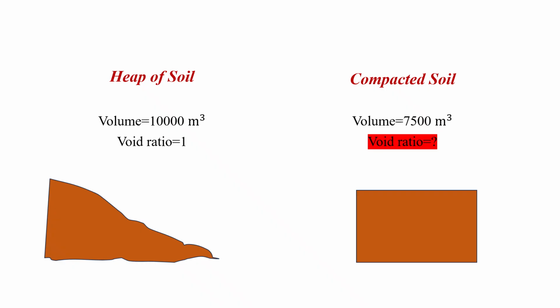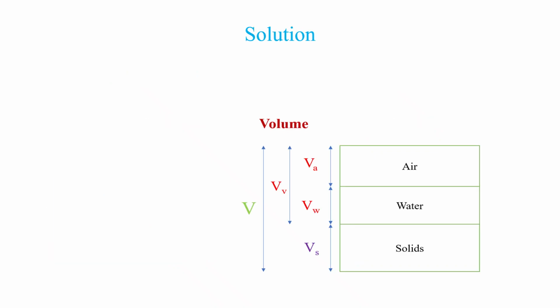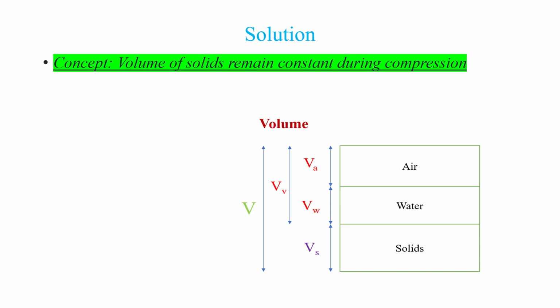We can see similar numericals where either a pit is made or an excavation is done and soil is used to make a fill or an embankment. Everywhere the concept used will be the same. So, what is the concept? The concept is that volume of solids remains constant during compression.